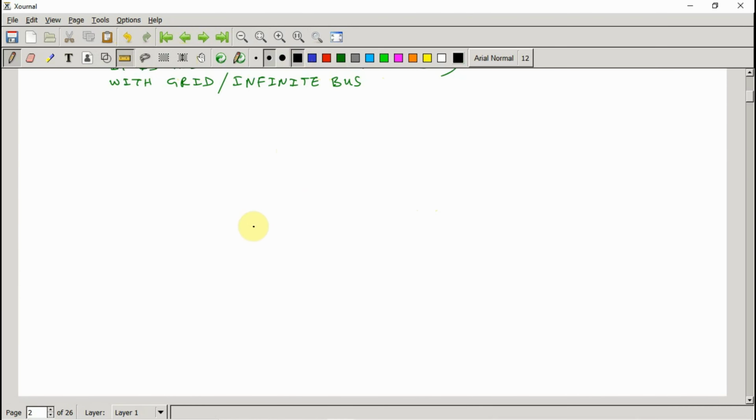So we will start with the terminal voltage Vt for the alternator. Here terminal voltage Vt, let us say, is the per phase voltage. So this is our terminal voltage Vt, our reference phasor. Now with respect to terminal voltage Vt, the armature current Ia is going to lag because it is a lagging power factor. So the armature current of the synchronous generator is lagging the terminal voltage Vt by angle theta. This is your power factor angle theta.